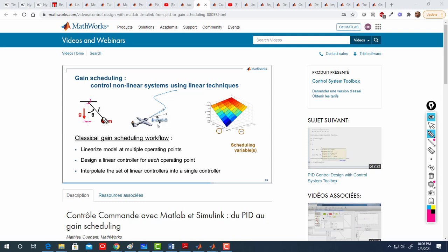Okay, so what if I ask you to control it to stay at this angle, like 45 degrees? You can linearize it around 45 degrees, find a transfer function around 45 degrees, and get a different PID controller for angle theta 1. What if I have angle theta 3?